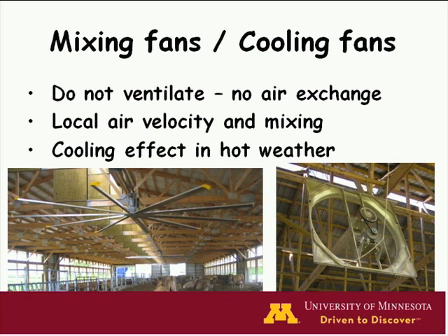Many livestock and poultry barns have mixing fans or cooling fans. And from our definition today, this does not provide ventilation, because this does not cause air exchange. It does cause mixing, and it creates a local air velocity, and it has a cooling effect in warm climates or climate conditions.